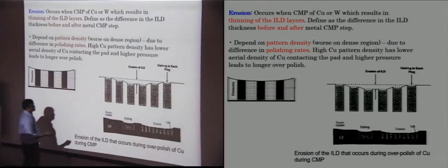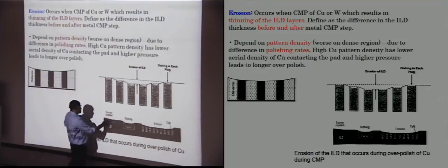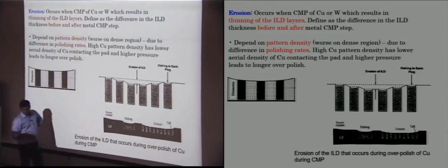Another problem shown over here is some residue and barrier left behind after polishing. No other process mechanically touches the surface of the wafer other than chemical mechanical polishing, so a lot of defects can happen if you are not very careful with the way you do it.